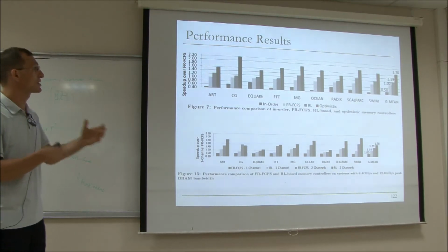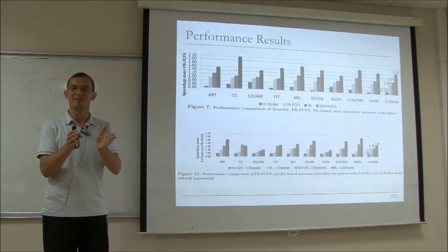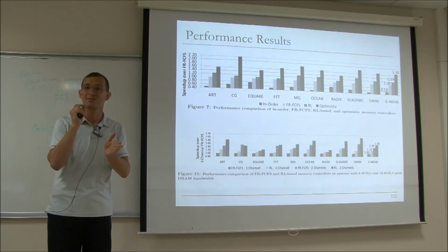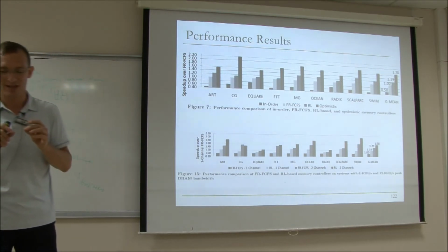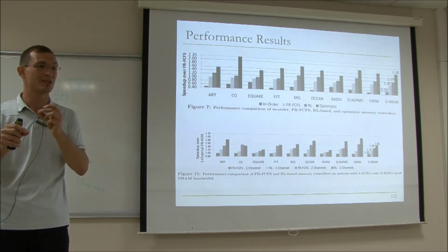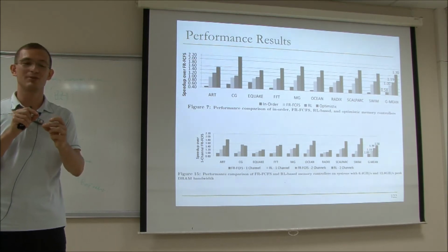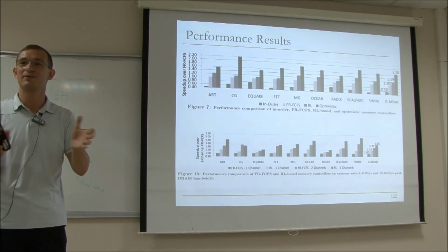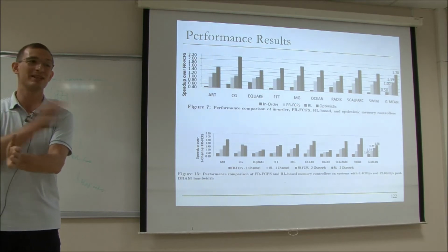And the reason is basically, if you do the scheduling in a myopic way by just looking at whether this will be a row hit, that doesn't maximize data bus utilization because there will be writes that will be coming in. So one example that I will give is current memory controllers cannot switch between reads and writes fast because there is a read to write switching penalty and a write to read switching penalty. As a result, they accumulate the writes, and writes are not critical. And once the write buffer is close to full, they switch to a mode saying, okay, now I'm going to service the writes, and the reads will be delayed.